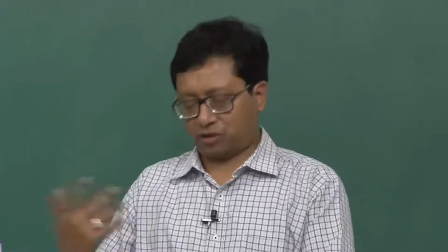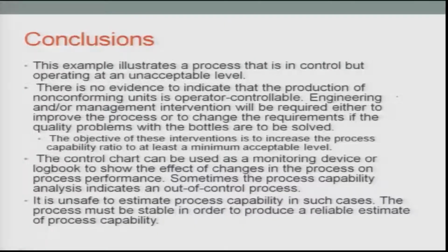So, in one case technically you are trying to find out the overall distances between the mean value and the lower control, or the mean value and the upper control, depending on whatever the case is, such that you are able to cover that area in such a way that it will give you the one-sided values. In another case you can find out the difference using the two-sided, such that those one-sided and two-sided examples which I gave would make much sense to find out the process capability and the process characteristics of the charts.